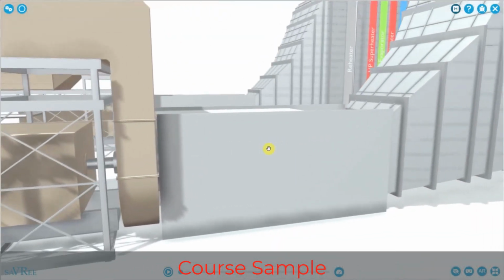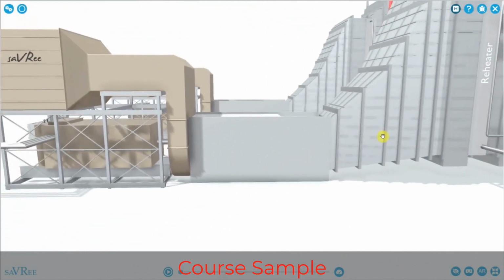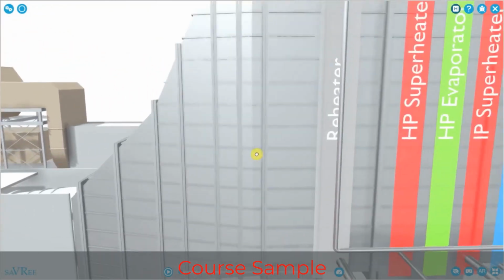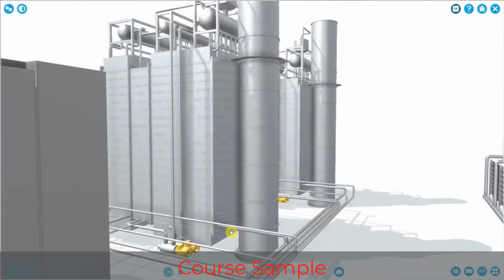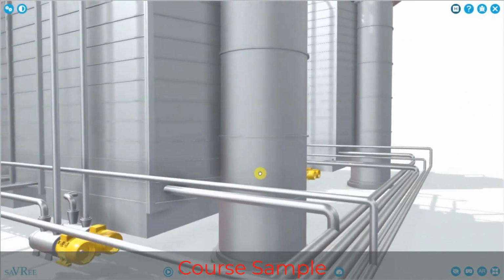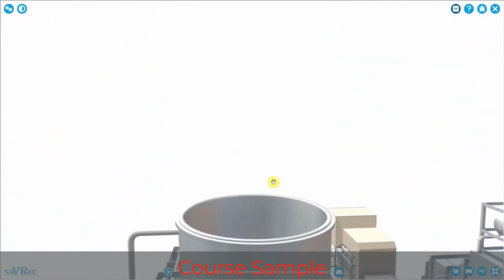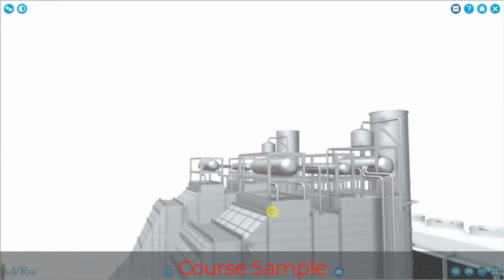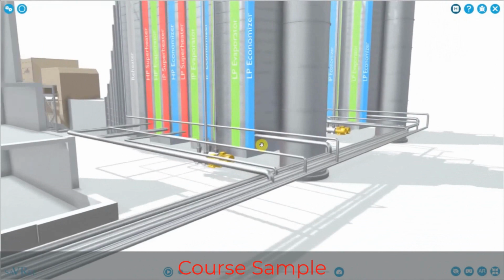What we could do, and what many plants have done in the past, is just send all of that hot gas, which is at about 600 degrees Celsius, 1150 degrees Fahrenheit roughly, out through a stack. So our hot gases would come in at the base of the stack here, let's say where my mouse is, and then they would flow upwards and out of the stack. All of that heat energy would be lost. You might be thinking to yourself, wow, what a waste. And you'd be right. In the past, this was not unusual. Energy was cheap.